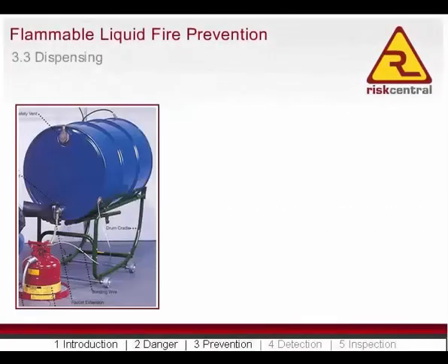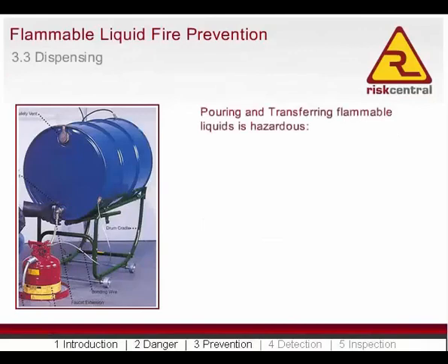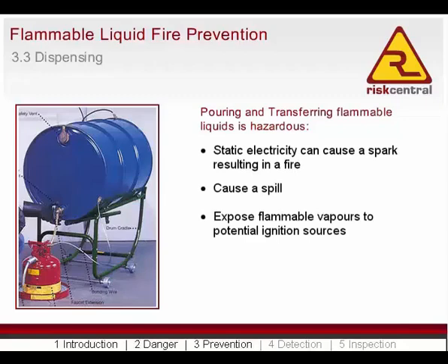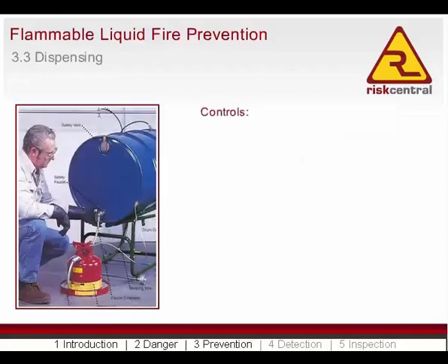Dispensing. The act of pouring or transferring flammable and combustible liquids from one container to another is hazardous because it can produce a build-up of static electricity which can cause a spark and start a fire, cause a spill, or expose flammable vapours to potential ignition sources. The most important controls to have in place when dispensing include the following.